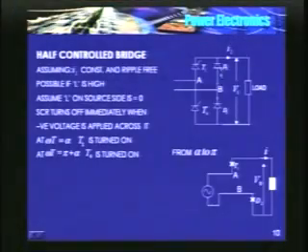How do we turn off T1? T1 turns off the moment D3 starts conducting. When the potential of B becomes higher than the potential of A, D3 starts conducting, and a negative line voltage appears across T1. Hence, this sort of turn-off process is known as line commutation.